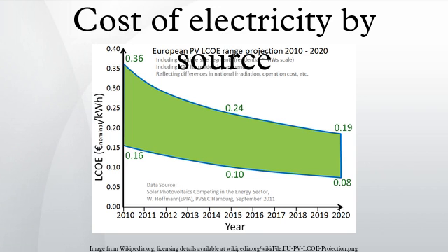In the case of self-consumption, payback time is calculated based on how much electricity is not bought from the grid. Additionally, using PV solar power to charge DC batteries, as used in plug-in hybrid electric vehicles and electric vehicles, leads to greater efficiencies, but higher costs. Traditionally, DC-generated electricity from solar PV must be converted to AC for buildings, at an average 10% loss during the conversion.